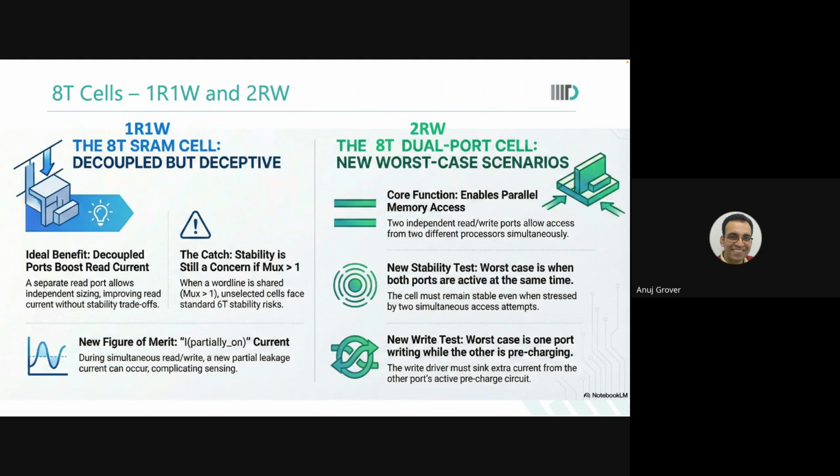So even if they arrive at the same time at the inputs, for this particular cell, this clock will arrive later than this clock. You cannot do anything about it. You have to design such that in all such circumstances, your system still has sufficient margins so that it doesn't fail.